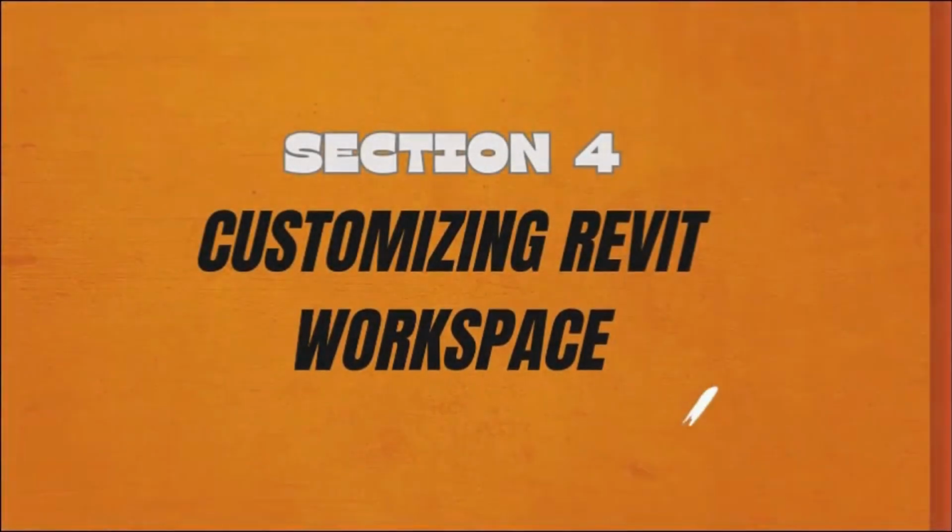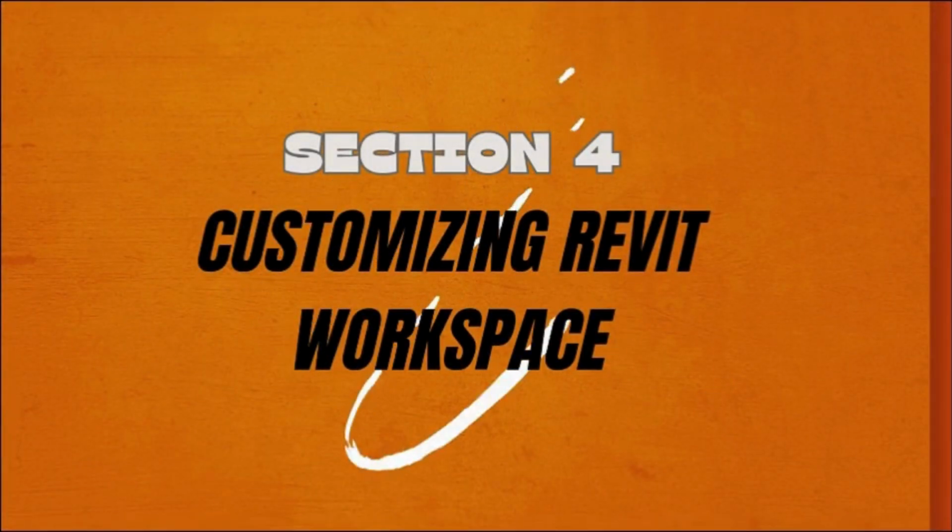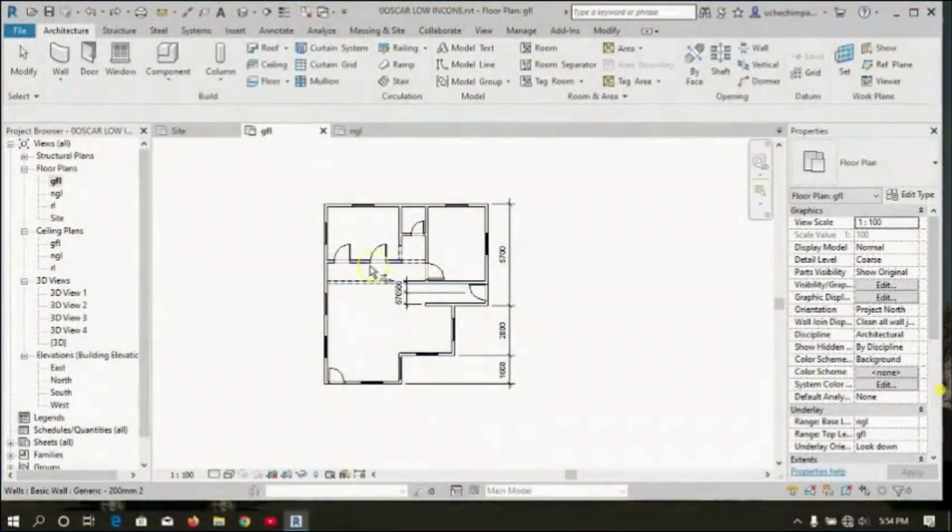In this session, I'm going to be teaching you how to make Revit work for you by customizing your Revit interface to fit your workflow depending on how you want it to be. So let's get into it. Let's start with the project browser and the property browser. Initially, as a first-time Revit user, the property browser and the project browser are usually on the same side, which is on the left side. But if you're not comfortable with that, you can adjust it, and I'm going to show you how to do that.